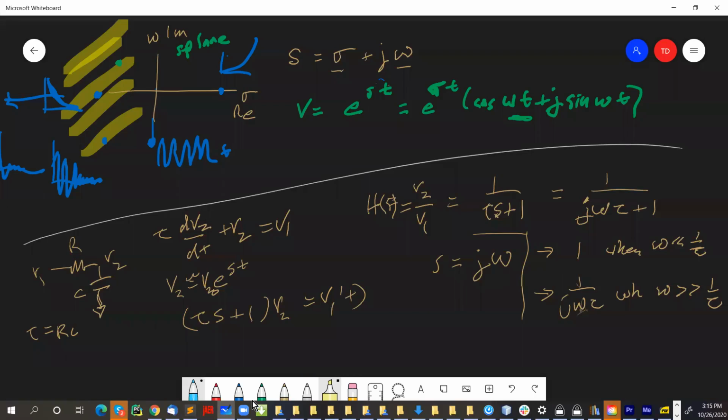Okay, I hope this is all kind of helpful as a gentle introduction to using Heaviside's cool methods for understanding the transfer functions. In order to really understand this, you have to go through a little bit of pain yourself and work out the complex arithmetic. In other words, you should work out with your own hands what is the form of the magnitude of H of s. If I want the magnitude of this function, you have to work out how to turn that complex number into a real number, which is the length of this vector. But you guys can work on that yourselves.